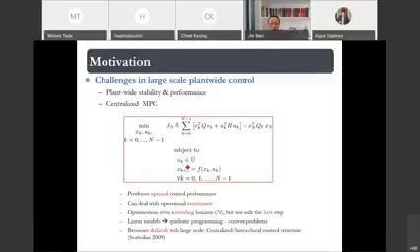And obviously we have a cost function. In the standard MPC, often we use a quadratic cost function, as those cost functions you use in optimal control. So it is typically a quadratic function of control error and the control action, together with the final cost.